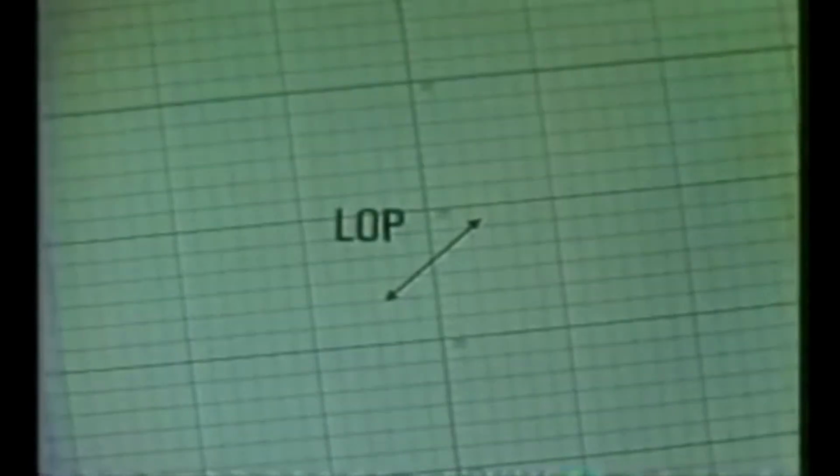Draw a line at right angles to the Zn line. This is a segment of the circle of equal altitude of your actual position at the time of the observation. Put barbs on each end. This is your celestial LOP. Label it with the source above the line and the time of the observation below.